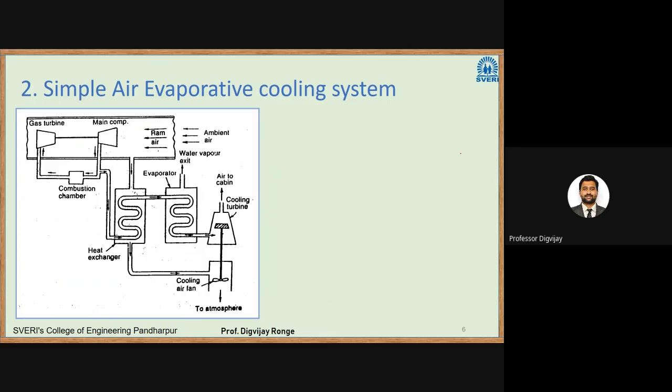And it is not necessary that we have to boil it. Even if you pour water on a surface, the water forms into water vapors, small gas particles. That process we also term evaporation. Even if you use air coolers in the summer, we are pouring water through a mesh. There is a fan in front of it, and that fan directly takes the water vapor from that mesh and throws it on the occupants. So that is also one type of evaporative cooling.